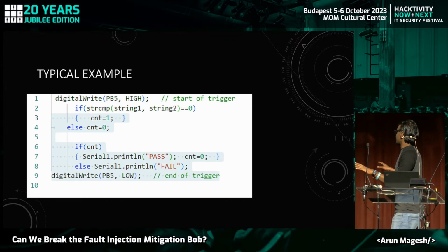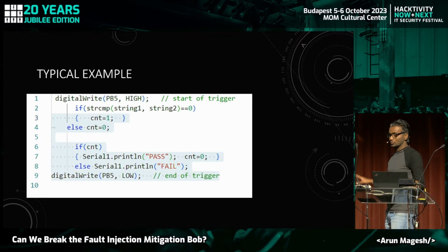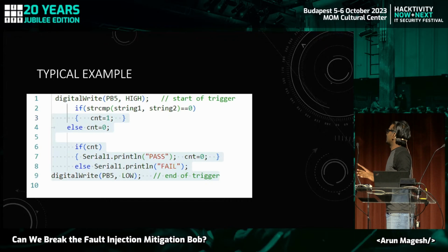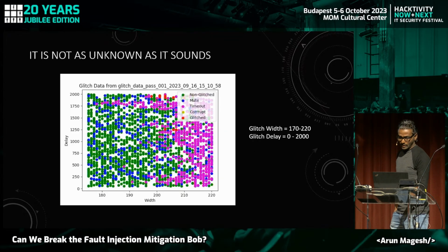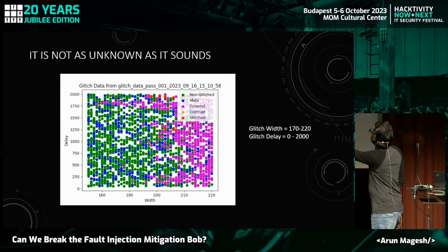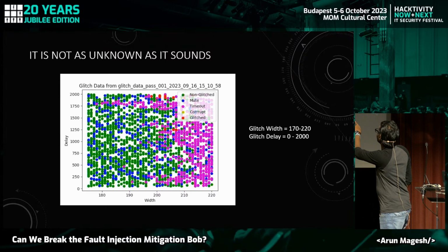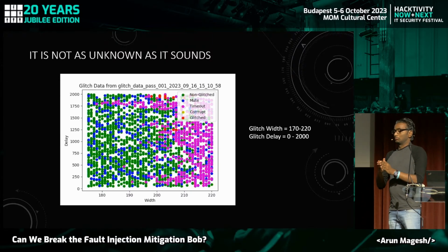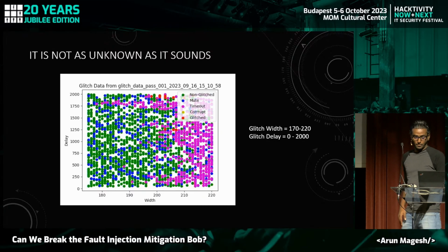So here, there's no protection. It's just as it is. It's how you would implement it. But if you think from a programmatic perspective, it looks perfect. Unless, for example, there's some hash collision, then you can bypass it. But technically, this seems like pretty secure code. But if I glitch it, you can see I can glitch it. If you look somewhere around 1250, you can see there are some reds, which means I could bypass it to get a pass value.